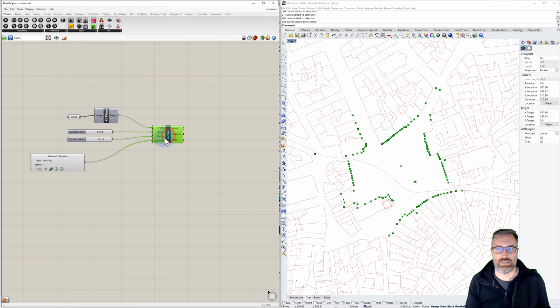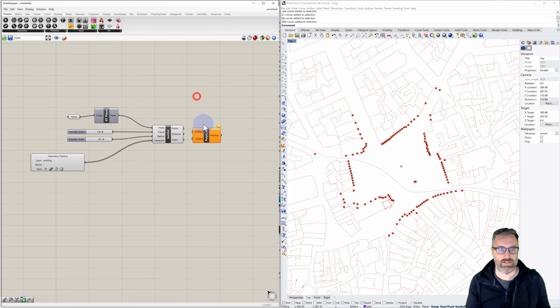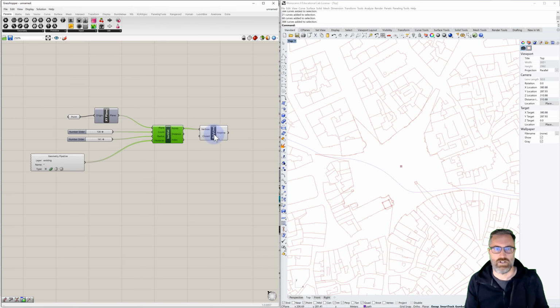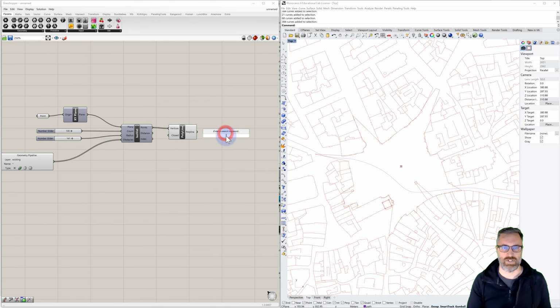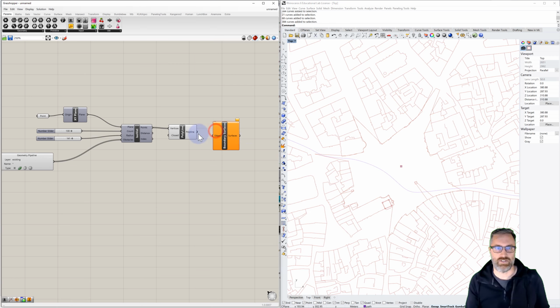And so this is a series of points. Here we can make, again, a polyline. We could connect all of these vertices, and let's see, is it closed? So now we can hide our points. We have a polyline that wraps around that, and we can do the same thing. We can make a boundary BREP, boundary surface.